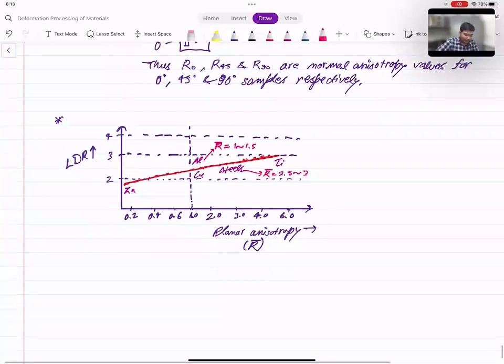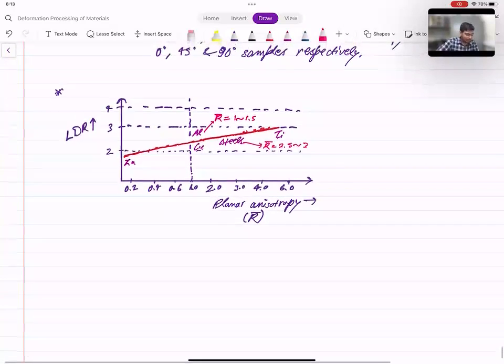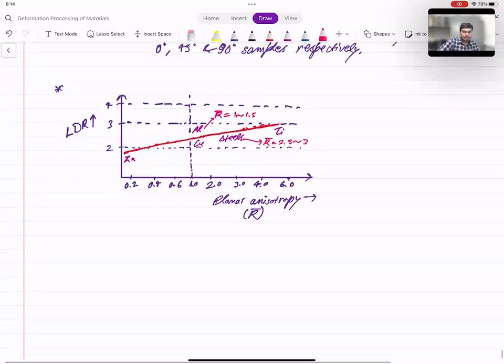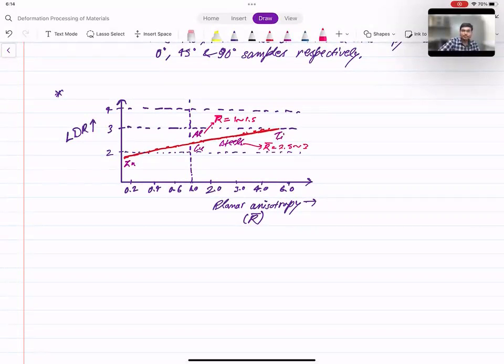And this gives us one more important piece of information, which is basically a sort of extra tip for you. You would have observed that both the zinc and titanium elements are HCP. But have you ever thought why is it difficult to deform zinc as compared to titanium? Upon deformation, zinc undergoes fracture or failure, while it is possible to deform titanium to some extent. So what could be the reason behind this? Okay. The reason for this is the C by A ratio of zinc and titanium.